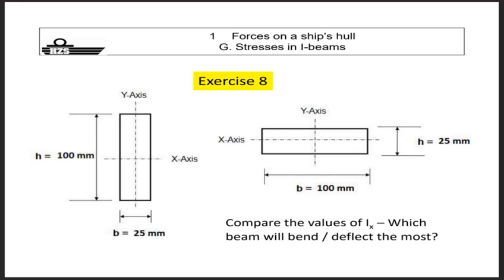Area moment of inertia, base multiplied by the height to the third divided by 12. And then you will see that the one from the first version will be a lot higher than this one, which is normal because the height is tremendously bigger than the one on the right hand side, and that is taken to the third, of course, is predominantly present.